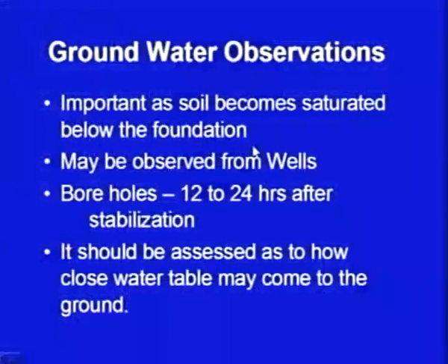The groundwater observations are also very important for foundation engineering problems. When the water table is high, the subsoil strata become saturated and it may enhance the settlements. Secondly, it may also reduce the shear strength. So, one objective of the soil exploration program is that we should know how much water table depth is there.